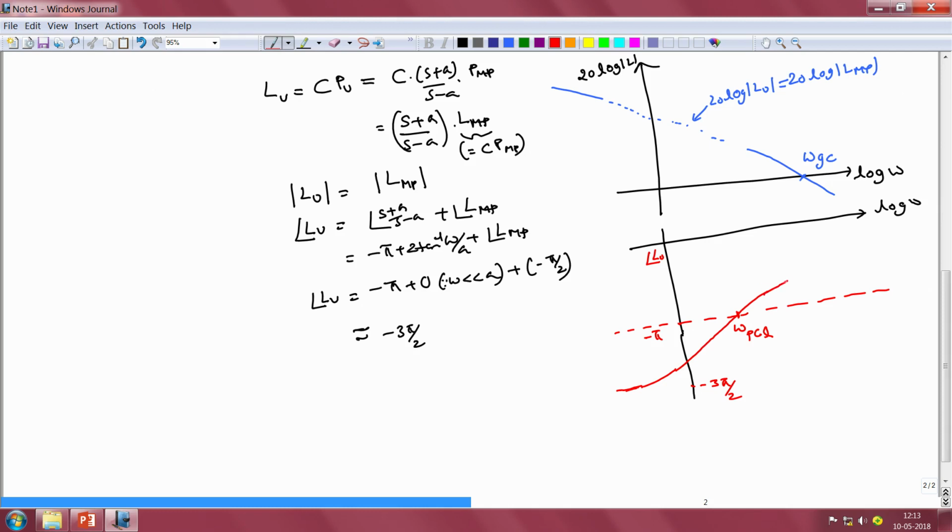and then it will continue to rise, but then there will be a frequency at which the other poles and zeros of the plant will start to contribute to phase lag. So this rise of phase as a function of frequency will be arrested by the phase lag contributed by the other poles and zeros of the plant and the controller, and hence the phase will start to once again decrease, and it will continue to decrease because this phase lag will increase with frequency, and that causes the phase characteristic to cross over once again.